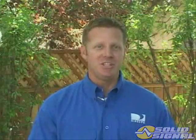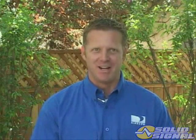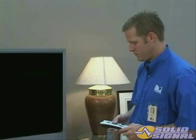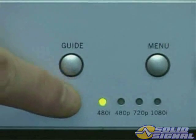When setting up the HD receiver and TV, it's important to follow the steps in the on-screen guided setup. When you turn on the TV set, you should get a clear picture. Though it'll be the initial setup screen, it should be clear and sharp. If you don't get a picture, check all of the connections, then check the format setting.